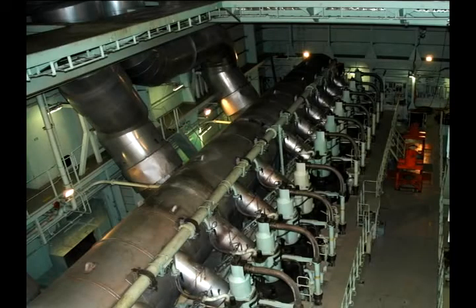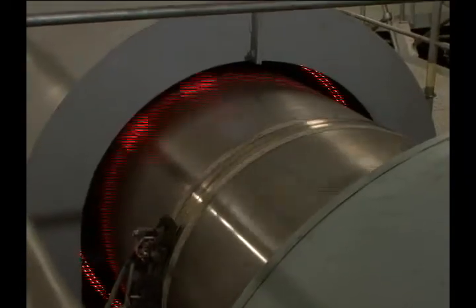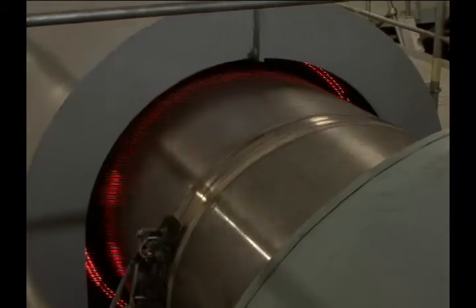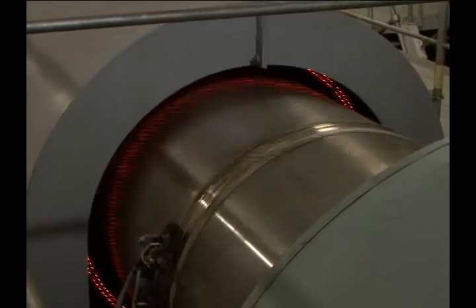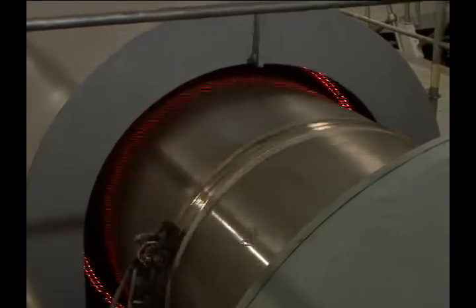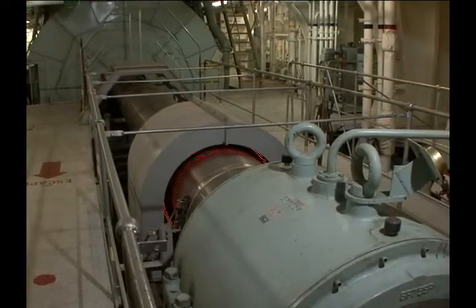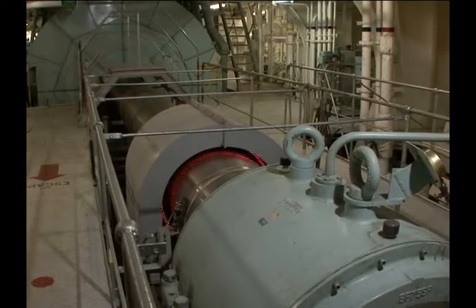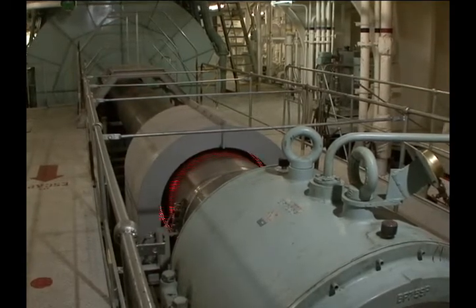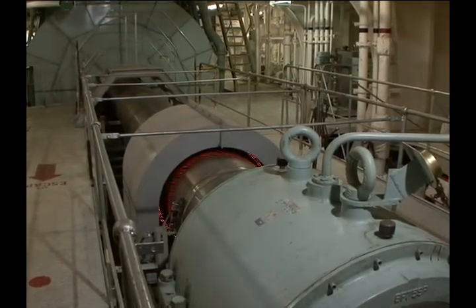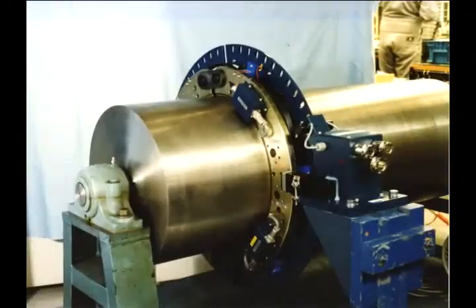It is necessary to measure torque in order to calculate the ship's shaft horsepower. The output of the main engine is transmitted through the countershaft. When this takes place, the countershaft is distorted slightly. Torque can be determined by measuring the degree of distortion exhibited by the countershaft. There are several methods of calculating distortion. Here, let's look at the most frequently used methods.